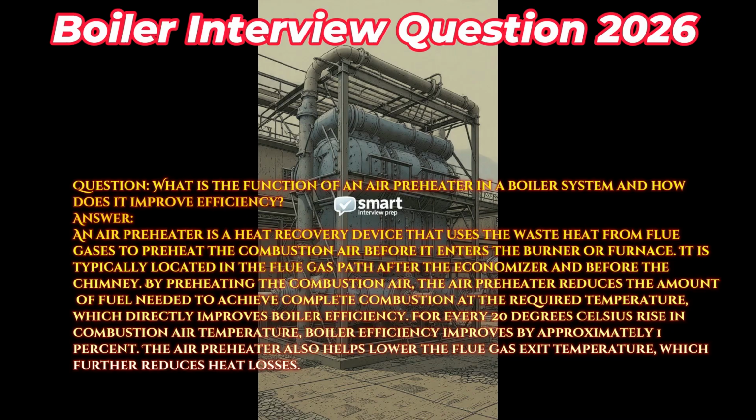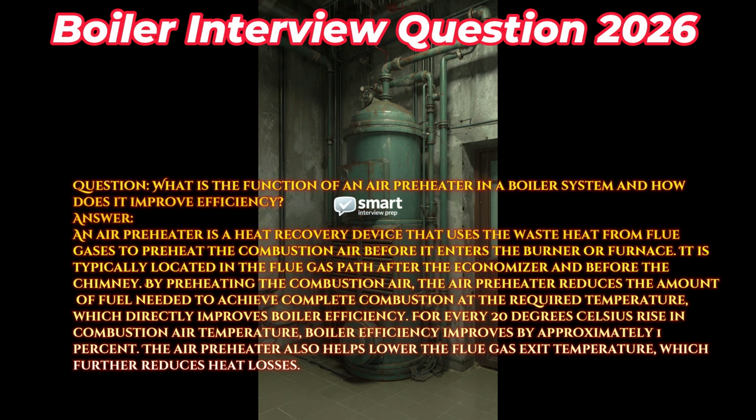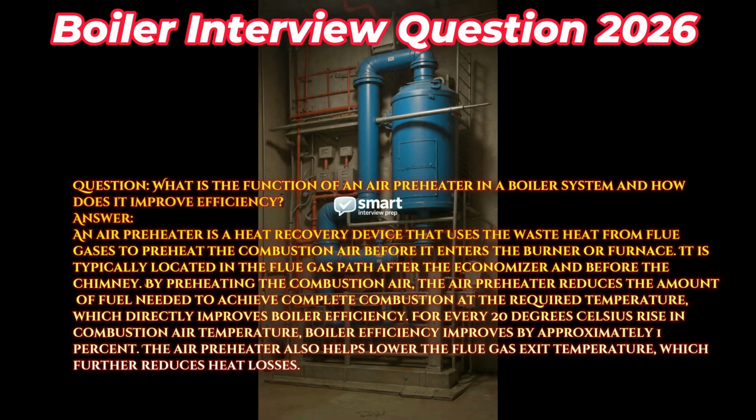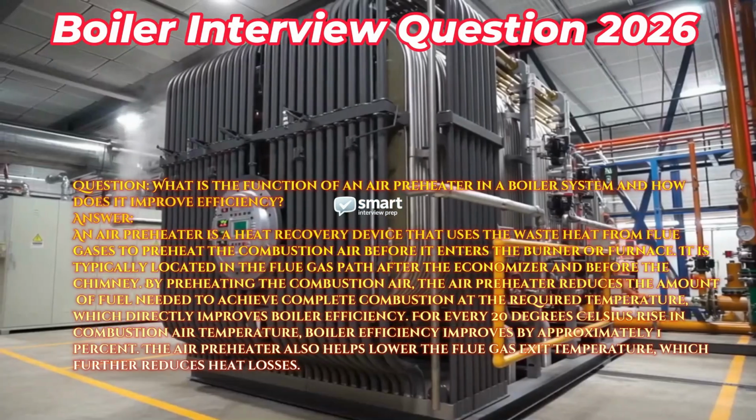Question: what is the function of an air preheater in a boiler system and how does it improve efficiency? Answer: An air preheater is a heat recovery device that uses the waste heat from flue gases to preheat the combustion air before it enters the burner or furnace. It is typically located in the flue gas path after the economizer and before the chimney.